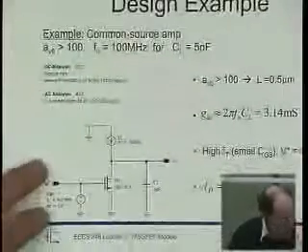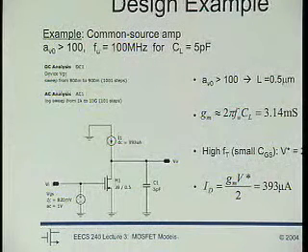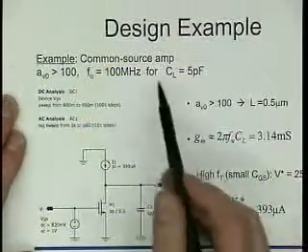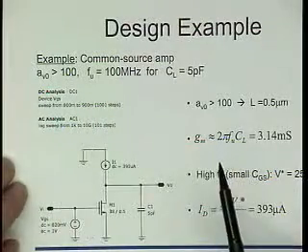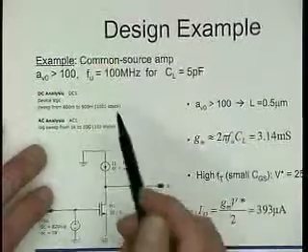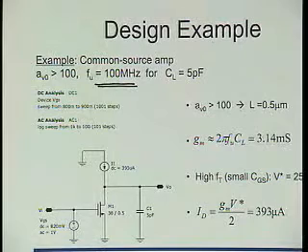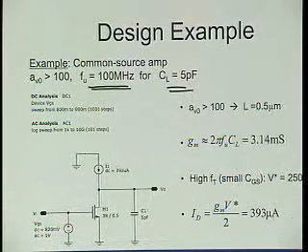Okay, now we pretty much have put things together. We can start designing circuits. And our start is going to be exactly what you have to design for the homework, a simple single transistor common source stage. So what we want is a common source amplifier. Anyways, I want high gain, right? I want a certain bandwidth. Well, the certain bandwidth, that is sort of understandable. My application tells me I need to have a bandwidth of 100 megahertz. And my application also tells me I better drive 5 picofarads at that speed.